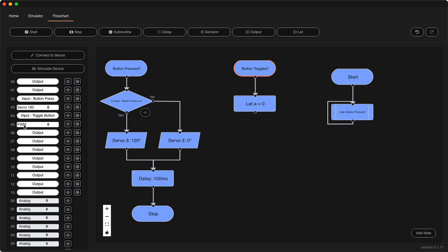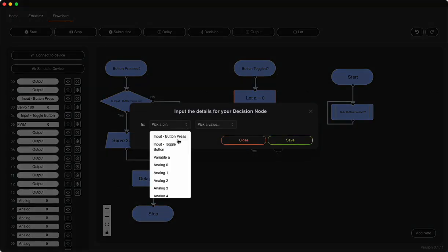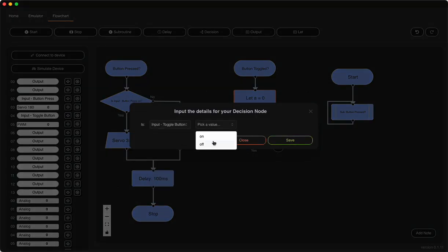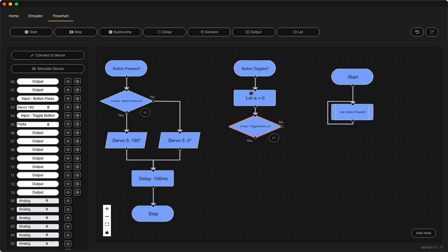So I'm going to use this on the PWM going from 0 to 125. So let's start there. Now I've set that now. What I want to be able to check again is that toggle button being pressed. So I'm going to keep this as the same way. So it's a normally open. So when it's pressed, it closes and goes high. So that's now there. So I've got that. I'm checking that. If it is pressed, that means I need to check this guy.